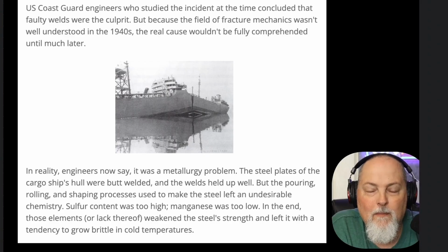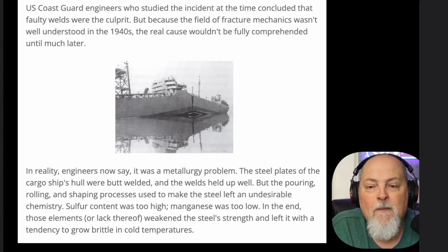There are a lot of examples. World War II taught us a lot about brittle fracture, unfortunately. A couple dozen ships cracked in half. One of the best examples was right down here on the Columbia River in Portland, the SS Schenectady. It cracked almost completely in half just while sitting dockside in 1943. The temperature difference, the existing flaws in the material and the low toughness let a crack just rip right through the vessel. And once a crack starts, it propagates pretty quickly.